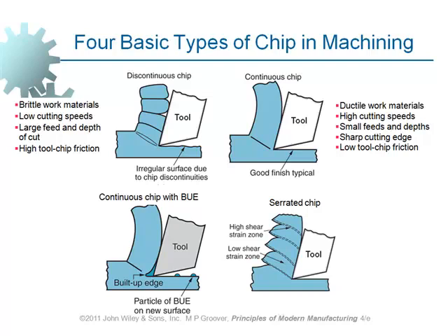And sometimes a rough surface is produced just like that, where particles of built-up edge weld themselves to the top surface of the workpiece. Meaning that the surface which is cut is smooth in the beginning, but some particles of the chip do weld themselves to the cutting tool, and after some time they are removed from the cutting tool and weld themselves to the top face of the material, which is called built-up edge. As a consequence, what we get is a rough surface. Despite the fact that we did cut a smooth surface, that's not what we have got in the end.